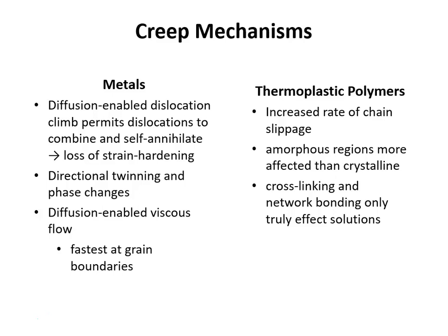This is possible with small parts using directional solidification, and that is in fact a routine strategy used for turbine blades, both for power generation and aircraft. So we are eliminating those diffusion freeways that allow creep to occur much more rapidly at a lower temperature.